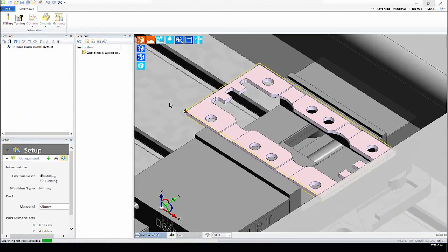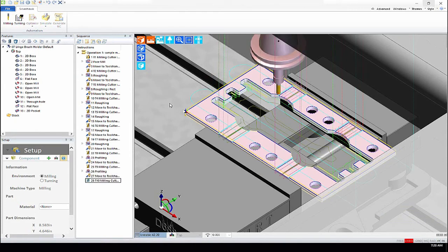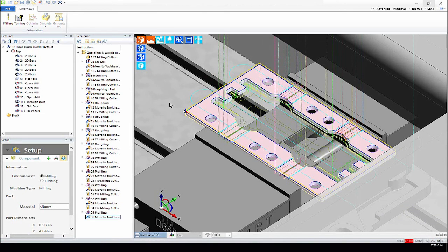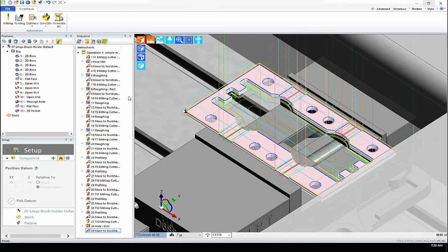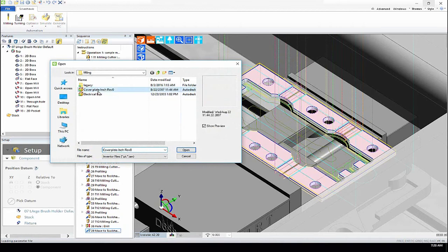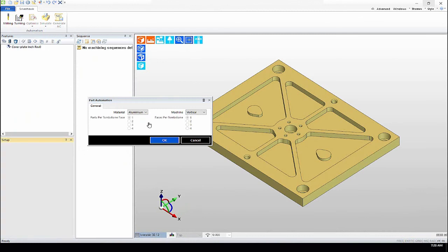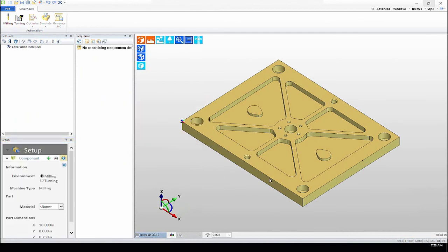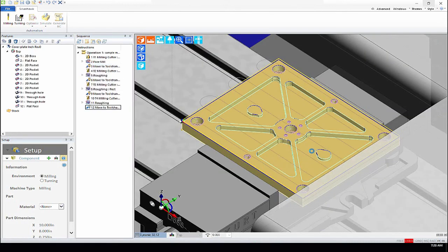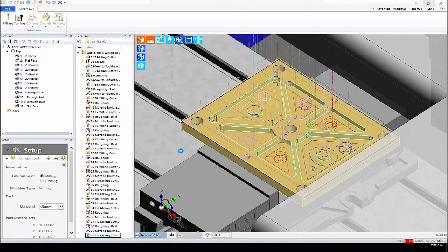So far, the parts are very similar, but the parts have required different tools and adapted the tool paths accordingly. The system can be configured for a very specific family of parts, but it isn't required. The next part is vastly different, and the system adapts to the new part, defining the stock according to the system parameters. It then picks the correct vise and places it on the machine. The tools and tool path are processed just as they were previously. It is now completely programmed and ready for the floor.